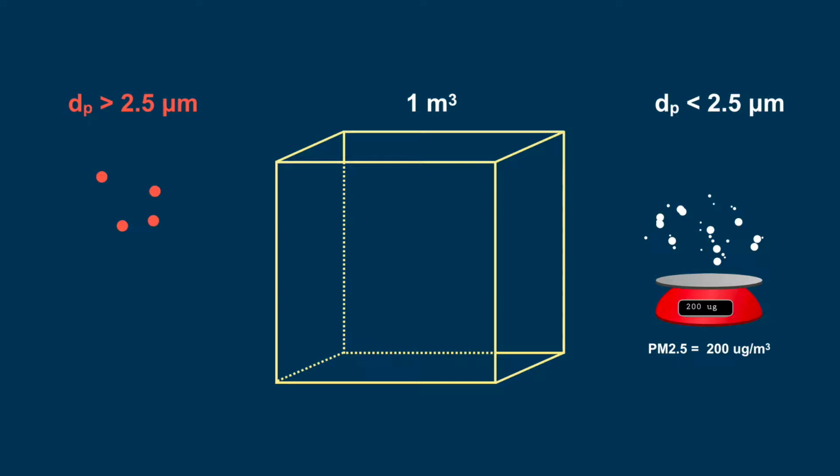While PM2.5 is typically discussed in terms of mass per unit volume of air, in cookstove testing we will also discuss PM2.5 in terms of mass of aerosol per mass of fuel burned, or mass of aerosol per unit energy delivered to the pot.